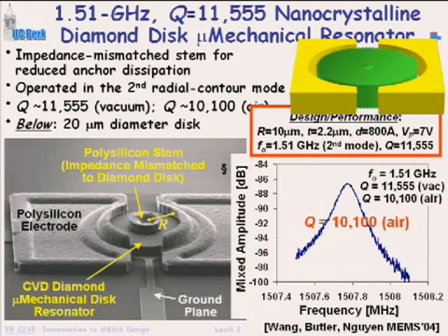In fact, that's exactly what an oscillator is. So if you do oscillator design, oscillators in their positive feedback loops actually kick the Q up to 10 to the 11th, 10 to the 15th. So you actually have such a high Q circuit that its time constant is so long that the oscillator stays, it's what you see as an oscillator, very stable frequency. Okay, that may be beyond some of what you recognize, but just the high Q here means it can have a lot of energy without you needing to consume a lot of power to give it a lot of energy.